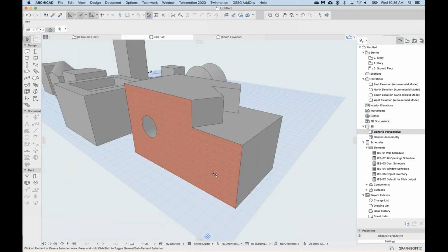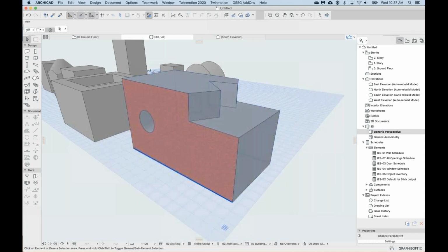Okay, so some more editing functions. We showed how to just draw on these surfaces and then use the push-pull. So we can modify this in another way. We can draw other morph elements, for example, and start doing Boolean operations, which can sometimes be easier.